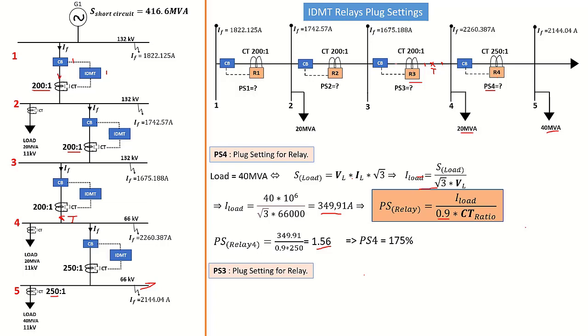That means this relay is only seeing the current going into the transformer, the primary current, not the current on the secondary, which feeds into these two busbars. So this relay does not see the fault or load current that goes into these busbars. It only sees the line current, or the primary current, going into this transformer at this point, before the 66 kilovolt point.